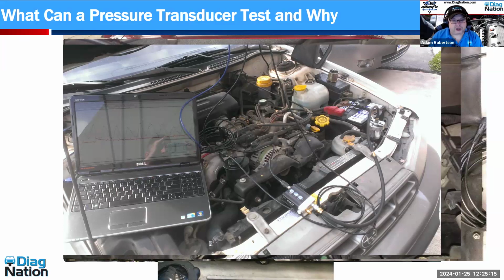A, I have lots that I can show you with blown head gaskets. Okay, that's a given. But I found something very unique. Most of you within the sound of my voice have probably done this. You filled up a cooling system, all right? And then you rev the engine up, the coolant level goes down, you top it off, then you jam the cap on. There's no doubt in my mind some of you do that. There's nothing wrong with it. I do it too. But when you rev the engine up, the water pump became more active and it drew down that water level, put a little bit of pressure in the block. So you got that extra cup or quart, whatever, of coolant in it.